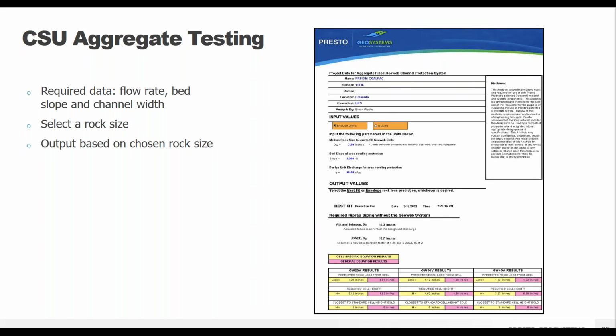So you can see how the size compares. A 2-inch stone versus a 10 or even a 16-inch stone. For this job, that stone reduction size was between 5 and 8 times. That's pretty significant. It's definitely something that you would want to consider if you have to truck in a lot of material. It's a lot easier to get smaller crushed aggregate than it is large riprap cobbles.